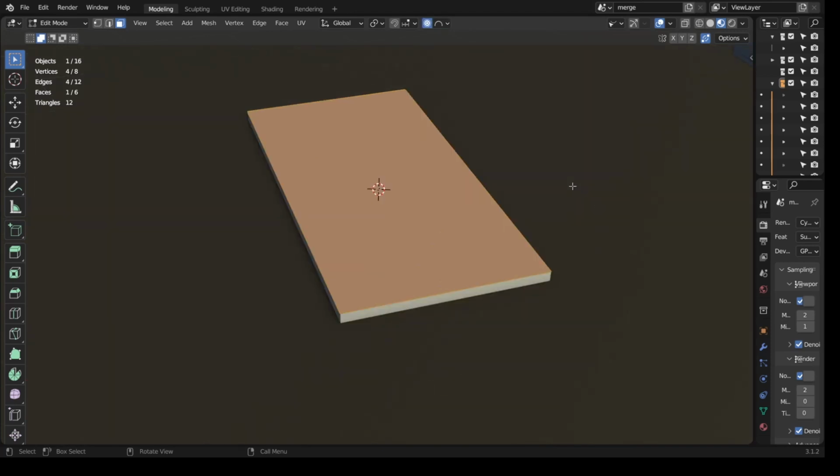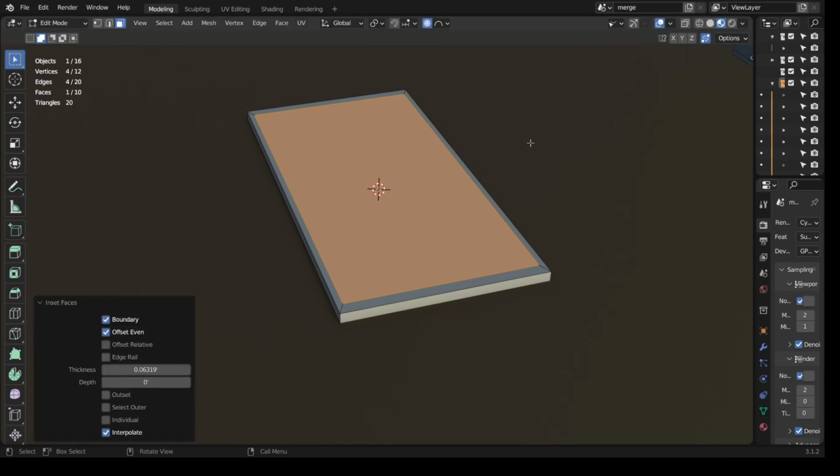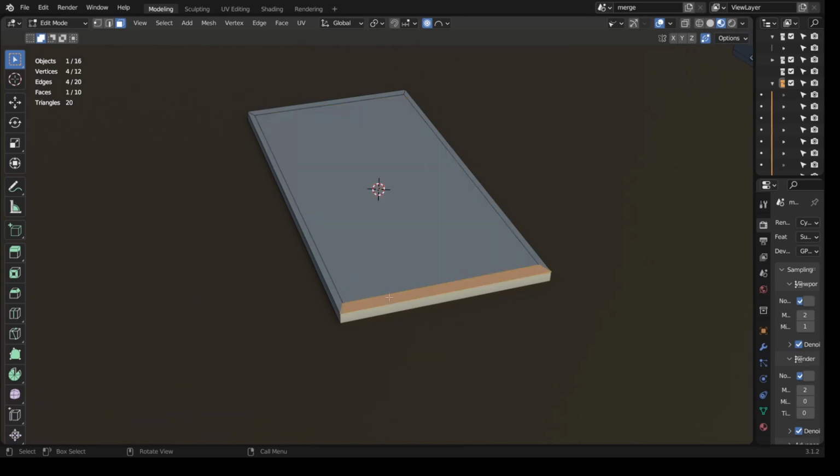Now what we want to do is pull up the walls around all four sides. So we use the inset key, I. We draw in the mouse until we get a proper thickness and click. Now we want to draw these four walls upward. So we select them one by one, shift, select, select, select.